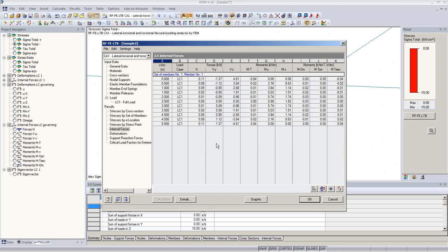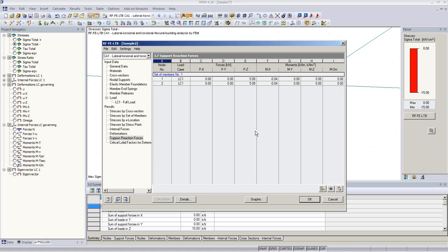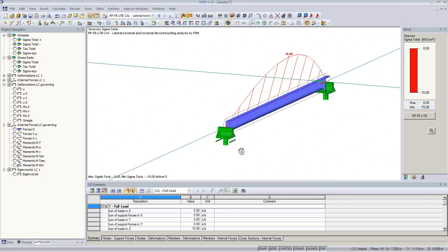So you can check all your structures, you get the deformations in numerical way, you get your rotation values here. You also have the support reactions. Also, a good piece of information is the twisting moment at the end from the imperfection, for example. That might be necessary to be taken over by the supporting structure for this purlin. We can take a look at it also graphically.